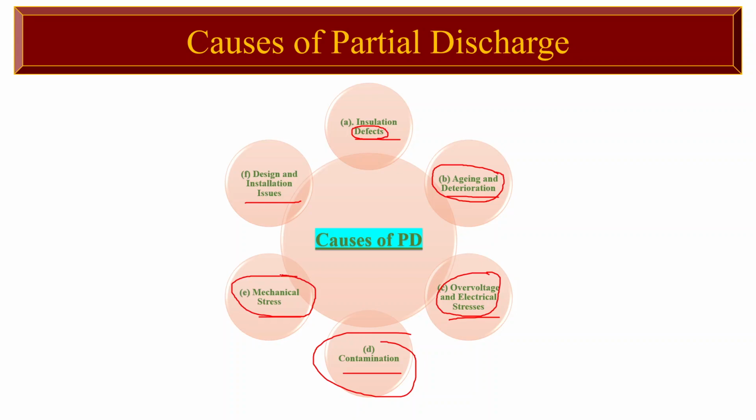Fifth one is mechanical stresses. Mechanical stresses such as vibrations and mechanical impacts can cause insulation movement, cracking, or separation. These mechanical stresses can create or worsen insulation defects, increasing the likelihood of partial discharge.